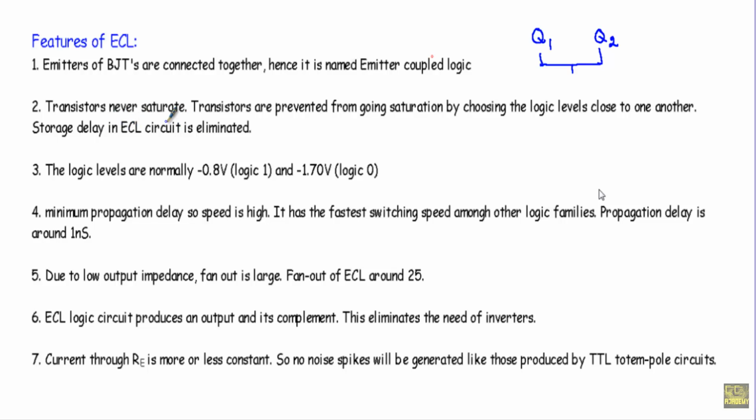Second one is that transistors never saturate. That means our transistor will operate either in the active region or in the cutoff region. So ECL logic circuits will be classified as non-saturated logic circuits. And in a non-saturated logic circuit, there is no storage time delay. Therefore, in the ECL logic circuits, you will see there will be no storage time delay.